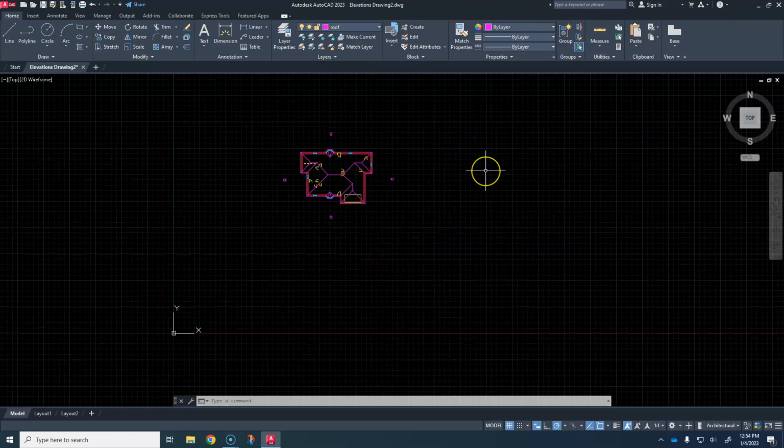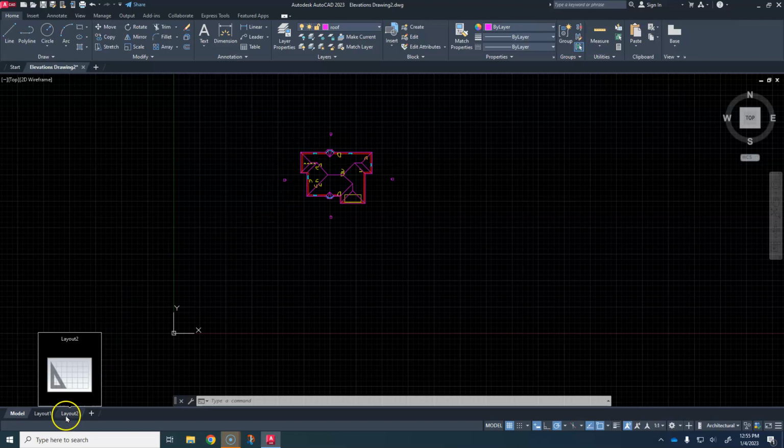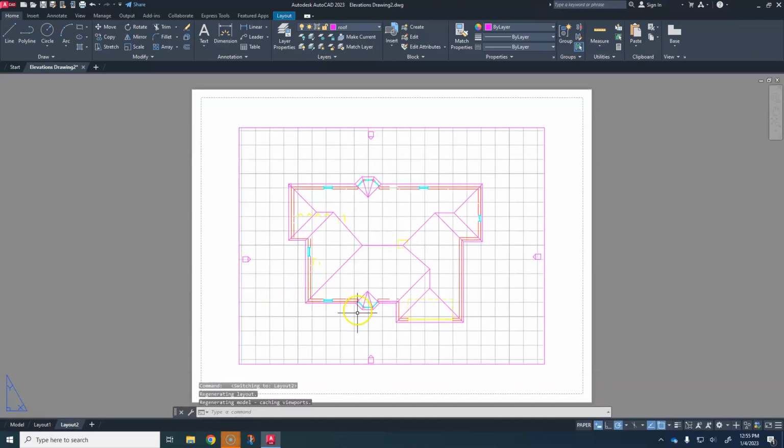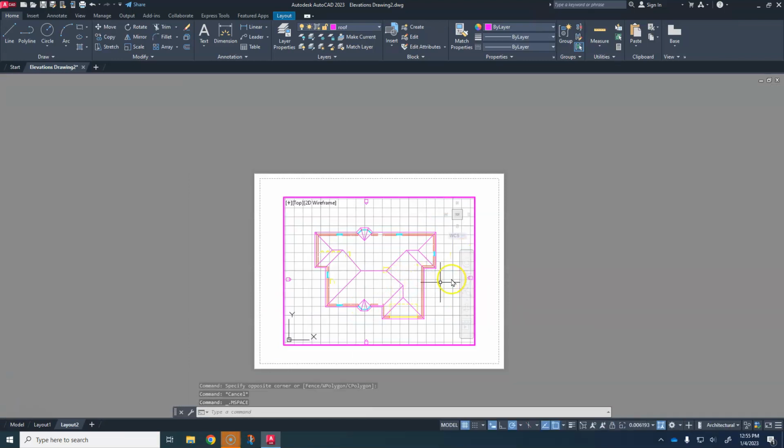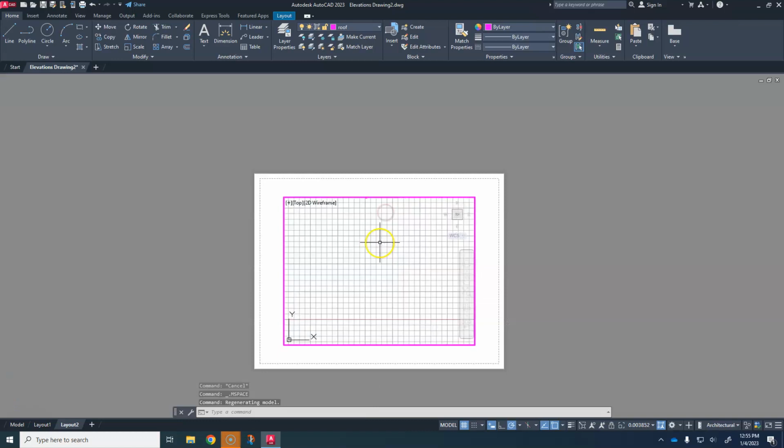And we draw those when it comes to AutoCAD. Now, I do have some software that works a little bit differently, but with AutoCAD, you pretty much draw everything right here on the same page. And it's all a matter of how you zoom into it on your layout pages. Like if I go to layout 2 here, okay, and I wanted to focus on just a certain drawing that's within this drawing, okay, I would double click and just focus in on that drawing.